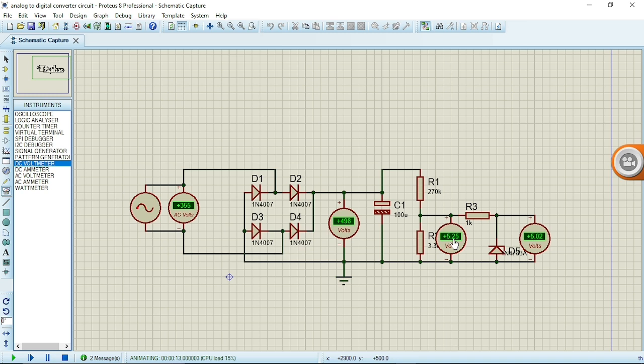If you are using any IC, you go online and look for the data sheet and see the properties, its tolerance and everything like that. But I assume 5.25 volts is too much for any IC that I want to be using. If you are using an Arduino, 5.25 volts is too much, though it can work. 5 volts is the maximum voltage that you can input into your Arduino.